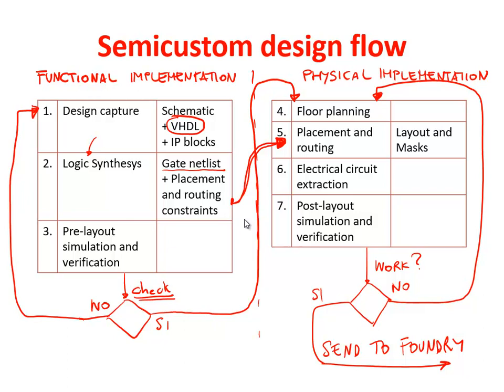At the design capture phase, one can use a schematic, or one can use VHDL, or a mix of VHDL for some blocks and directly an electrical circuit schematic for other blocks. And in that phase, one can use large IP blocks taken from a library. So, starting from that, one can use a logic synthesis tool and transform the initial design into a gate netlist